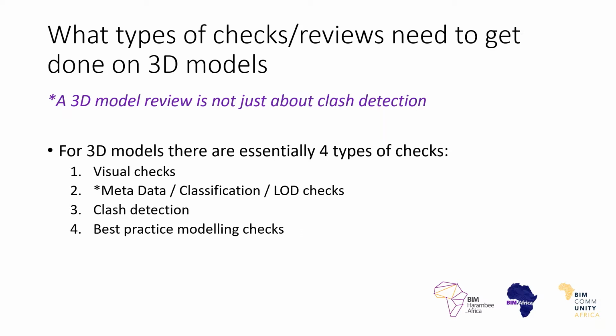While you're still in a design development process, a lot of stuff's changing. If you're trying to resolve clashes of elements that are still most likely going to be moving around and changing, clash detection can very quickly become counterproductive. You can spend a lot of time doing clashing when things are actually still going to change. That then results in abortive work.